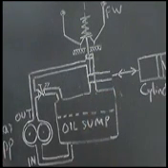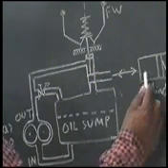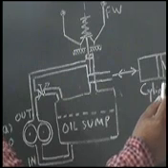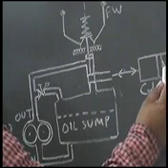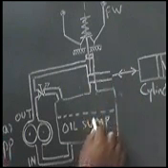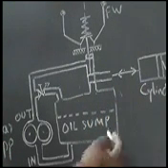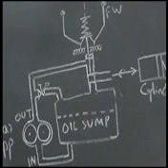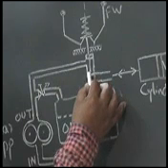And what will happen? There will be a connection between the cylinder and the sump. In that case, the oil from the cylinder, as it is a spring loaded piston cylinder, will release some oil and it will drain to the sump, till the RPM has been reset to the setting of the needed RPM, and at that point it again comes back and closes the port.